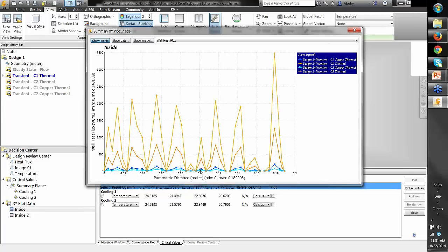So the rate where the cooling starts and where it ends, you start building in residual stresses. And these are the type of things that we're trying to design out of the part, but at the same time, we're also allowing you to take those residual stresses into a structural tool to find out what the strength is.